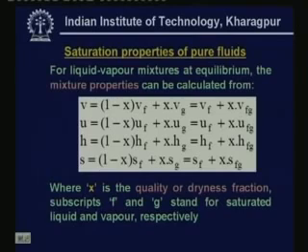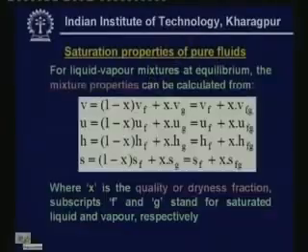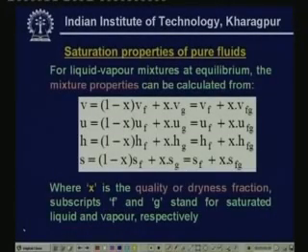Now let us look at the saturation properties of pure fluids. What do we mean by saturation properties? Again I would like to repeat that most of the time we will be dealing with liquid and gas either in the single phase, two phase, or superheated regions. So how do we evaluate the properties of liquid-gas mixtures in two phase regions? The equations shown here are for finding the two phase properties, that means liquid-gas equilibrium properties.